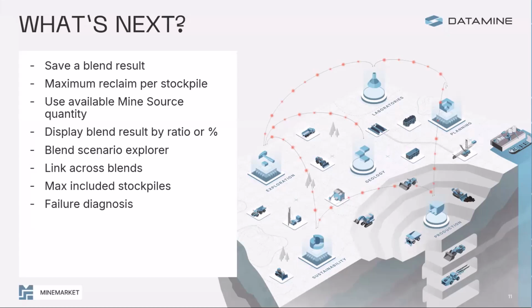We also are going to include a maximum number of stockpiles to include in a blend. At the moment, MineMarket will just go for as many stockpiles as it needs to generate the blend. But what we're going to do is provide a limiting capability within the blending functionality that allows you to specify how many stockpiles to include in the final blend result. And why that's important is because your operation may only be able to reclaim from, say, 2 or 3 stockpiles. You may not be able to reclaim from 6, 7, 8 stockpiles, which the blending algorithm might tell you are required. So by putting in a maximum number of stockpiles, we can limit that to match operational limitations.